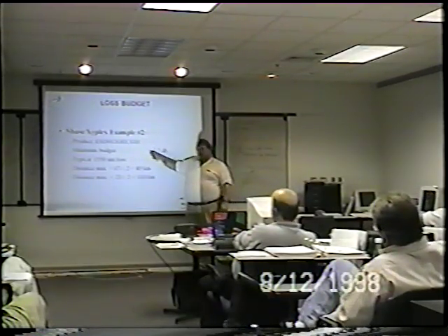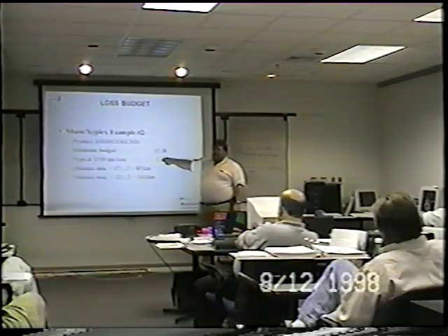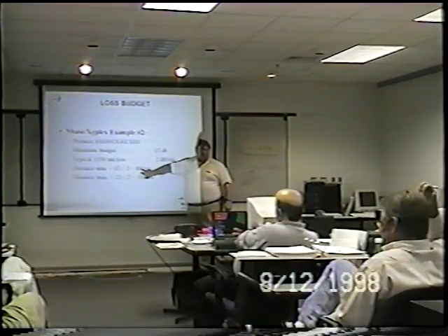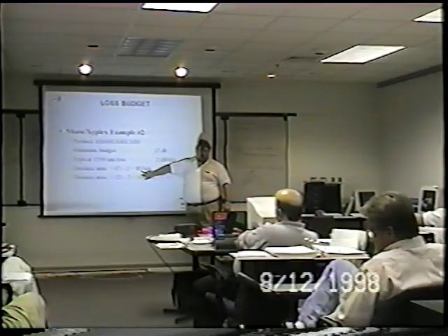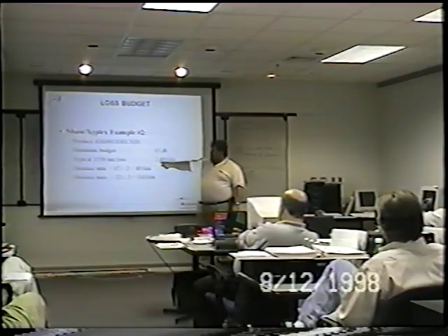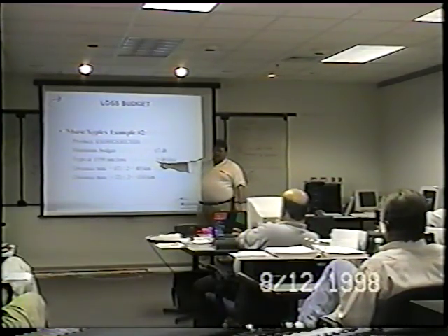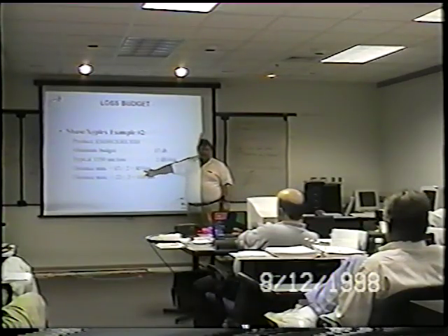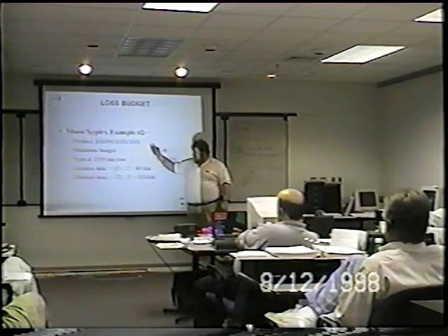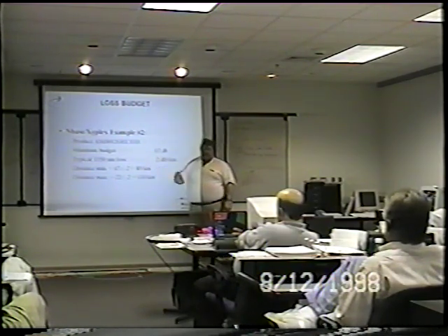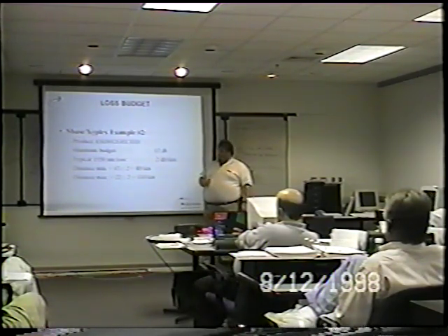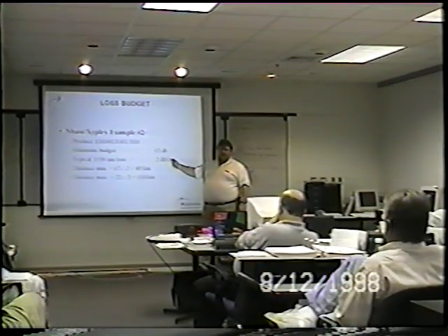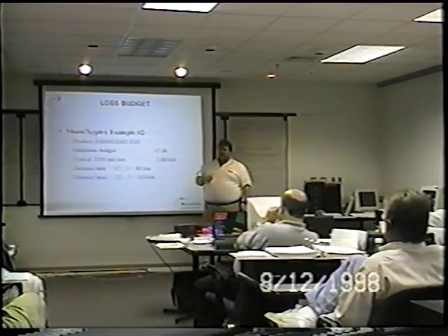Now, when you're operating at 1550, the slightest variation in connector loss, link loss in the fiber, and so on will make a dramatic change on the end-to-end distance. If you were to simply add 0.2 dB per kilometer on that fiber, I'll cut those distances slap in half. Our range then is between 40 and 50 kilometers. So you've got to make sure you've got real tight controls over these kinds of fiber plants, because those little minute changes can be killers.